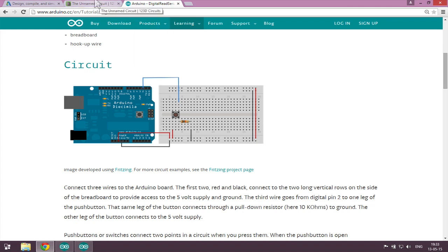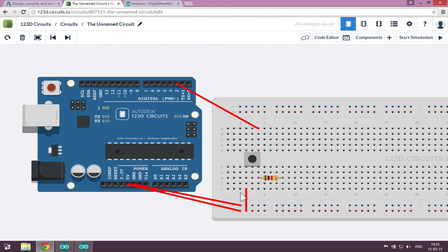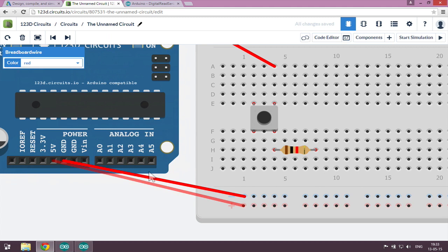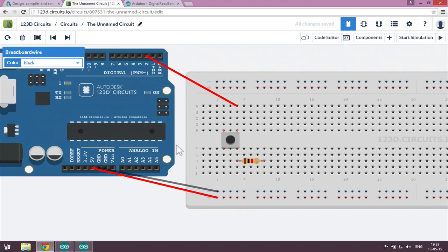Oh, I did it the wrong way around. I should also color code. This is the best way to. So +5 is this one here, and this one here is the ground. Just mark it black. So now it's a lot easier to distinguish between plus and minus if you use colors on your wires. Your actual wires should also resemble these colors, because if you're working with voltage, plus voltage and minus voltage, always use red and black cables.